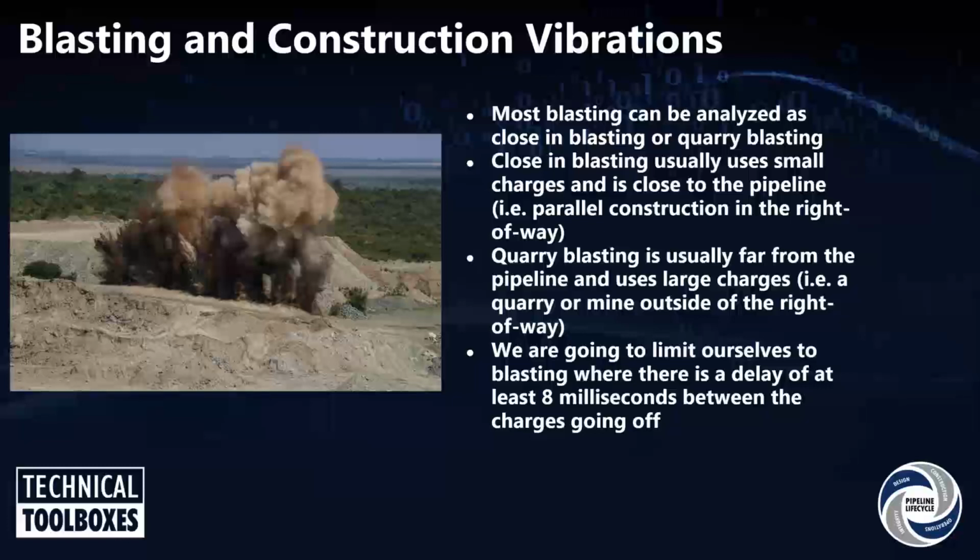You might be somewhere in between, not too far away, but far away enough that you are not sure whether you can use Esparza's equations. If you are somewhere in between, you can use both methods. You can assume it's quarry blasting and use the quarry blasting equations and methods, and then assume this is close blasting and use Esparza's, and take the answer that's more conservative. So the next slide, please.